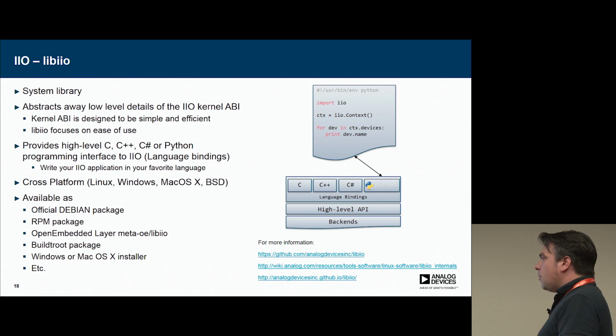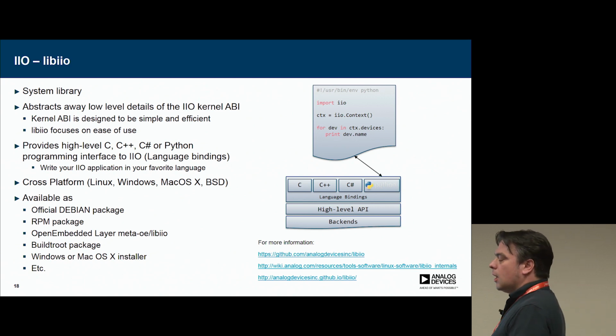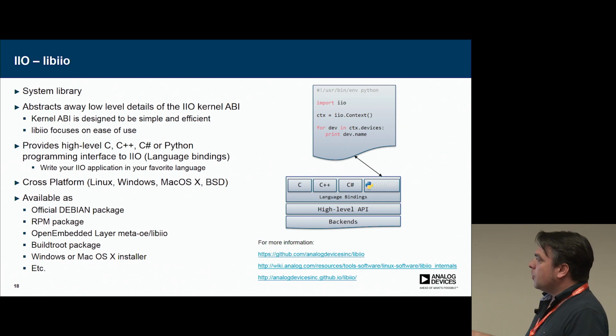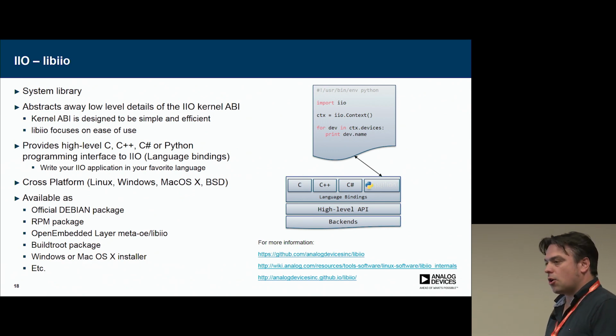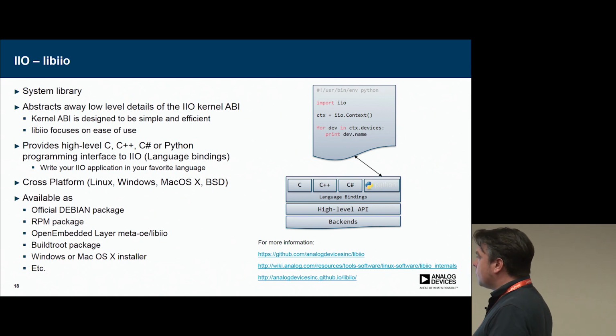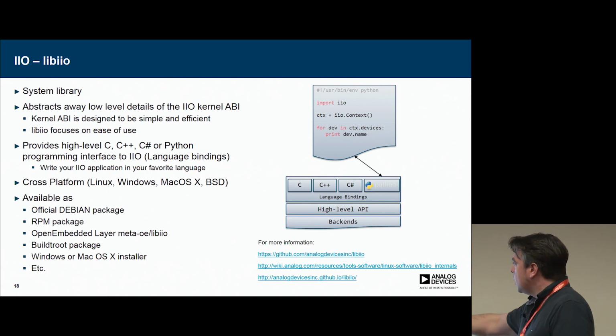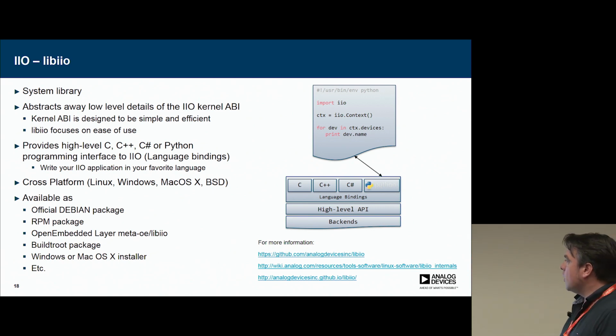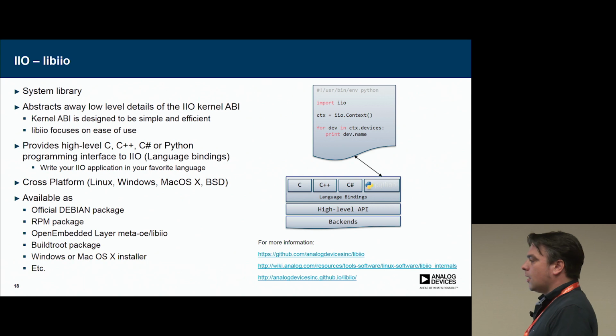It really focuses on ease of use for handling IIO devices. It provides several language bindings, so there's support for C, C++, C#, Python. And so everyone can write their IIO application in their favorite language. So there's an example for Python. You import iio, then you create a context, and then you just loop over all the devices and print their name.